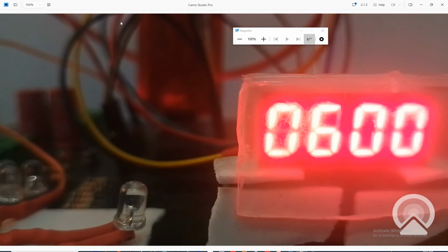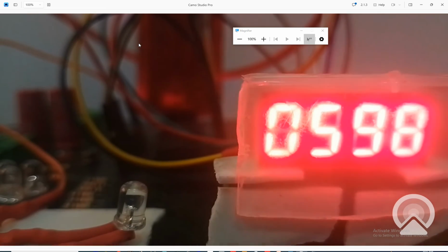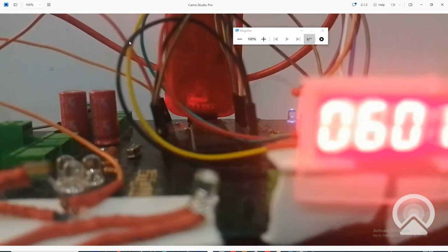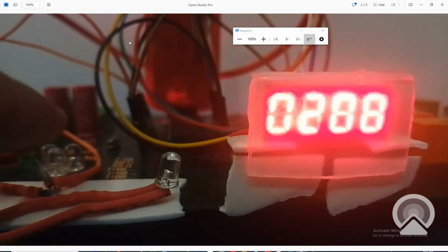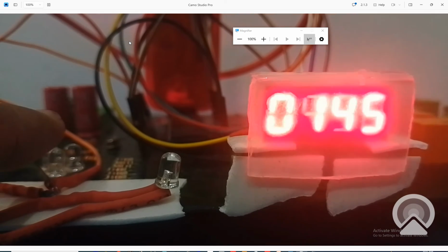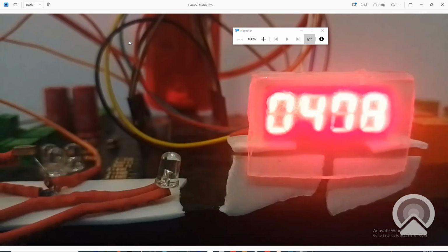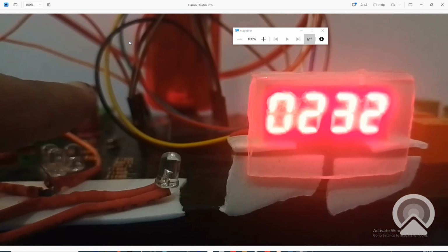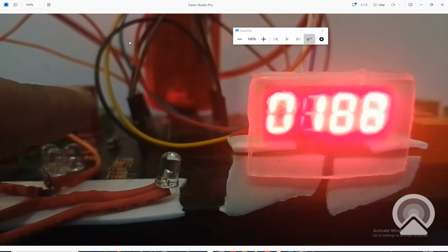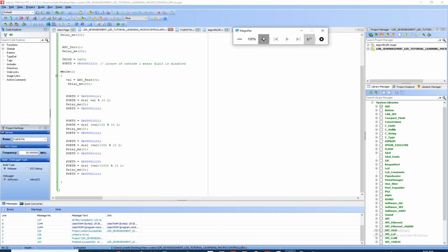See that it's working fine. It's like 600. So now we program the LED that whenever the value drops below, so I place the finger. See, it's like 130, 140. So let me lower down the light by placing a hand on it. So it falls below 595. So I bring the finger above it. It's like 250. So what I do is that if the value goes below 200, then the LED must turn on. That's the condition I add.